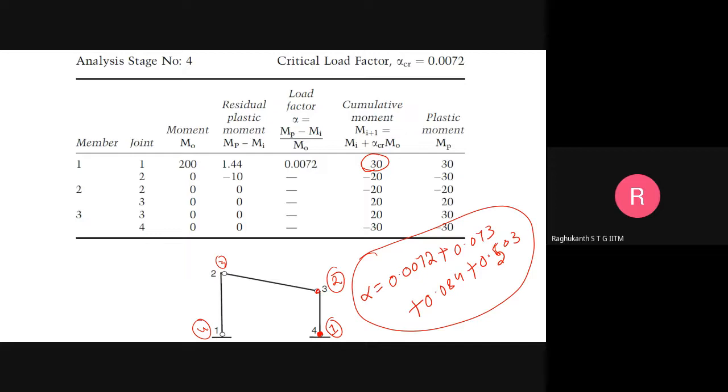So it is something like, if you draw the moment versus curvature, it is linear up to some place. So the first plastic hinge forms. Then the whole portal frame has changed. Initially it was fixed. Now one side it is fixed. The fourth plastic hinge forms. So after that, this is our analysis. Now once again, joint 3 plastic hinge formed. Then once again, this one other plastic hinge has formed. Then once again you follow, another plastic hinge gets formed, and then it goes like this actually. Okay, so this is how.